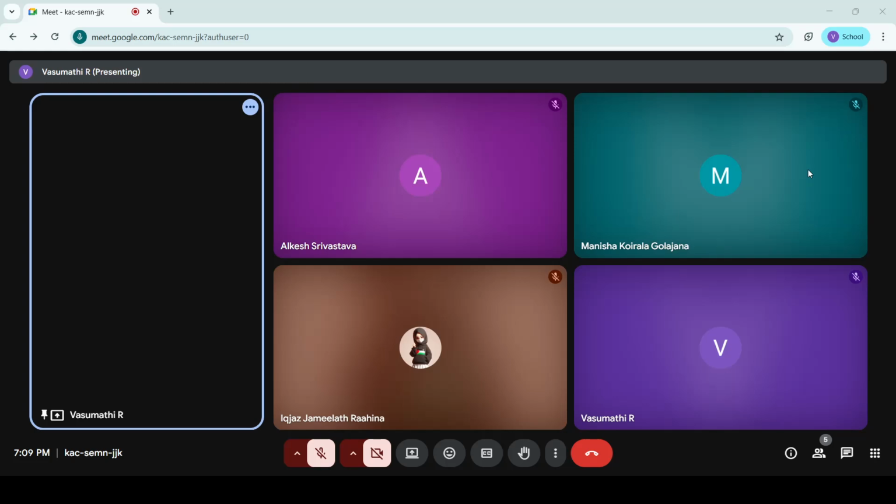Just expand it in terms of Laplace transform. So if you write a Laplace transform for the circuit, first if both the elements are in parallel, how will you write it? L into C by L plus C, right? So the Laplace transform of this will be L di by dt into 1 by C into integral i dt divided by L di by dt plus 1 by C integral i dt.